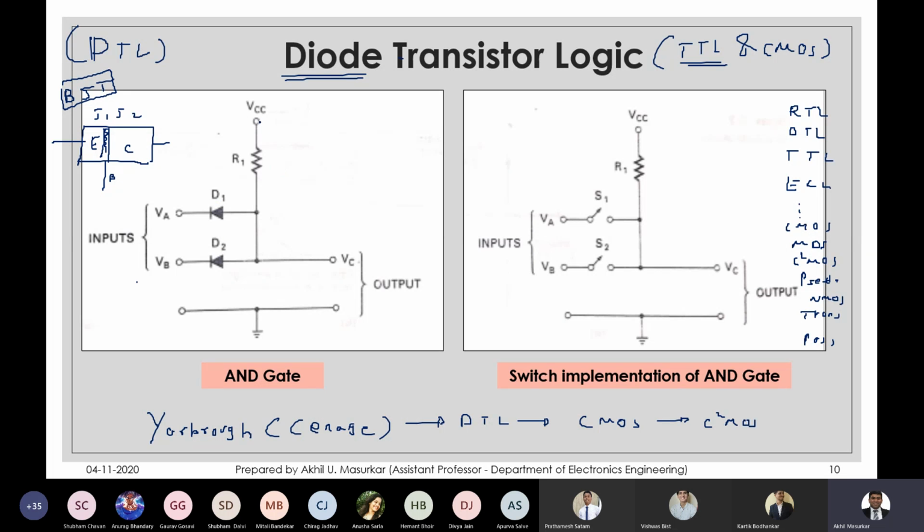This is VCC. Let's say this is 5 volts. So the current flowing is going to be 0 for the time being, because you can see that there is no closed path available as such. So if the voltage drop across R1 is 0 for the time being, what you will have here is 5 volts, and here also you will have 5 volts.